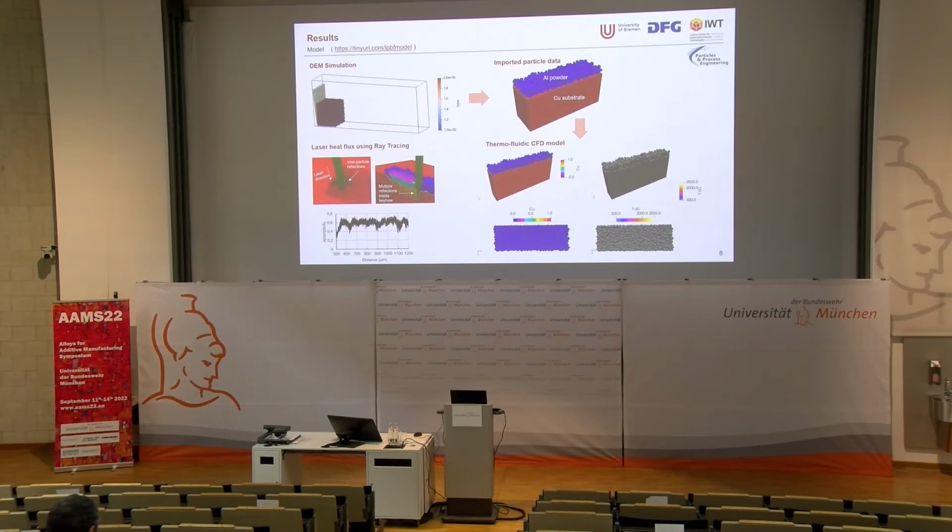When the laser moves from point A to point B, this algorithm can also give the data about how much energy is absorbed by the metal. So we can calculate the amount of energy that is absorbed by the material. Because of multiple reflections, the energy absorbed by the material is quite high. The base metal has an absorptivity of around 10%, but due to multiple reflections, it goes up to around 60%.